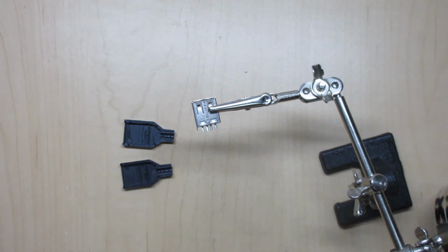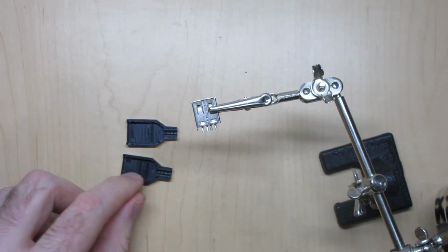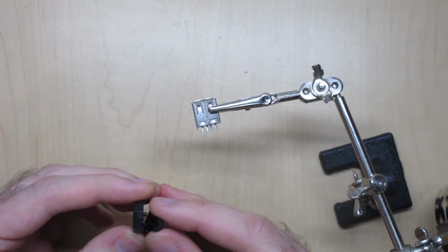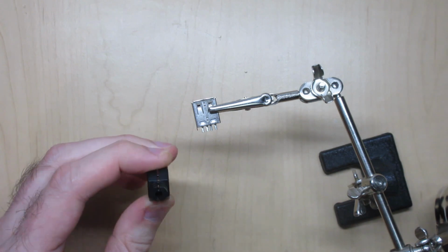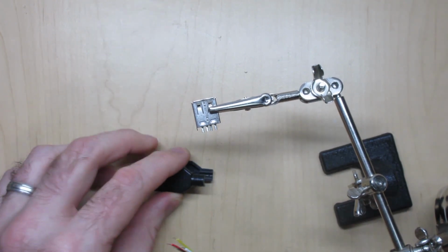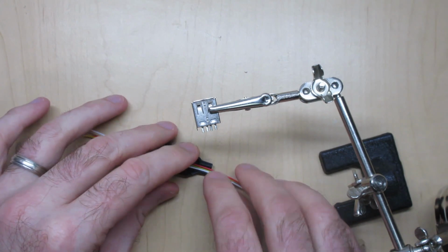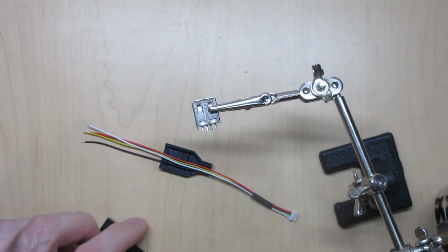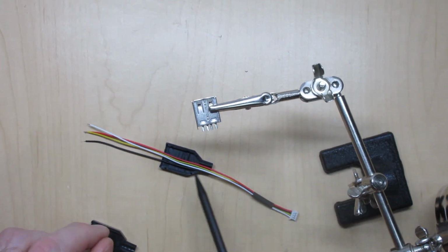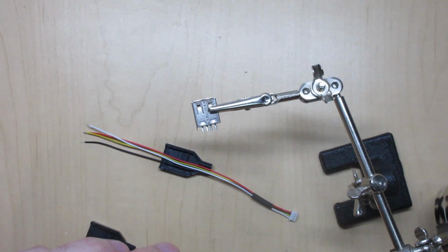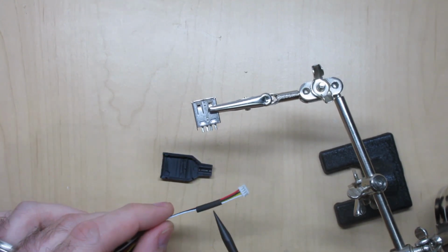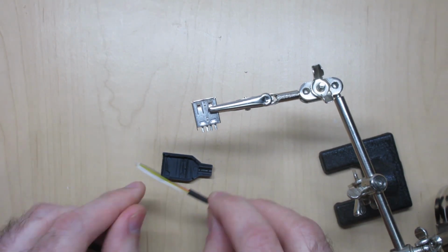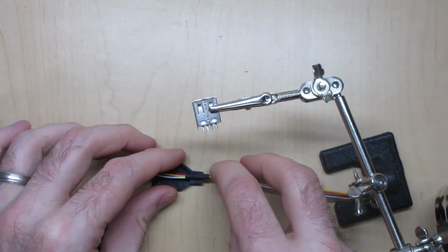As I was preparing to solder this USB terminal, I noticed that the plastic enclosure isn't going to put much compression on the cable once it's fully attached to it. You can see there's still quite a bit of room there, even though it's not fully sealed, and the wires that go in here, they can pretty much wiggle around. There's quite a bit of space for them to move freely. So I'm a little concerned about the strain relief that we could potentially put on here. It's effectively non-existent. So to help out with that, I put a little bit of heat shrink tubing on the wire ahead of time. I think what I'll do is I will have this slide up and it will rest somewhere in here.